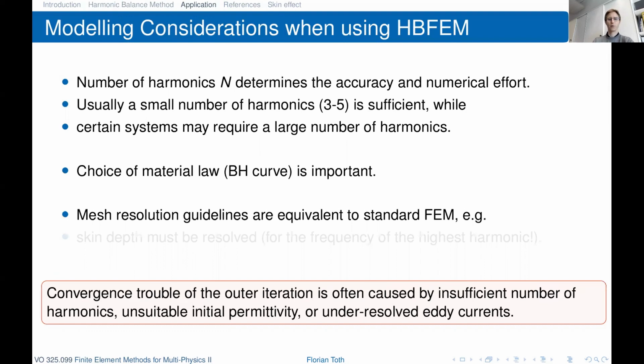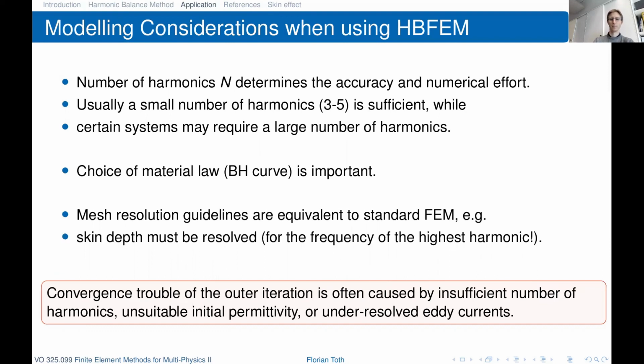The mesh resolution guidelines are actually equivalent to the standard finite element method. So there's no difference there. The important thing here, we're dealing with the eddy current problem, so the skin depth must be resolved. An important side remark for the frequency of the highest harmonic: the skin depth is frequency dependent, and what is important is not the base period, but actually the highest harmonic we're considering in our analysis.